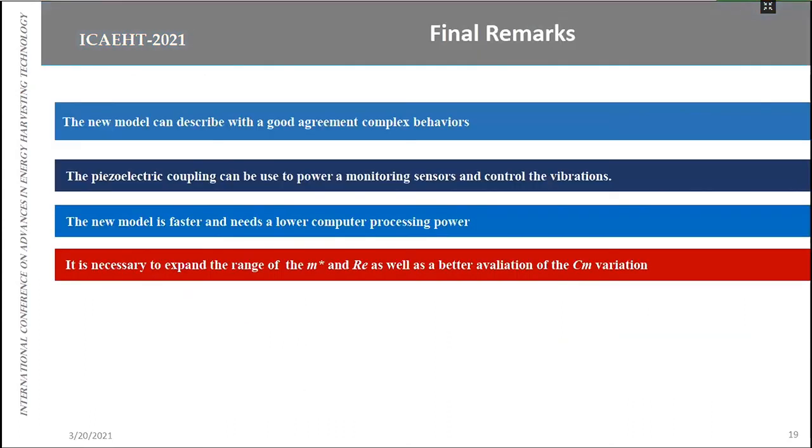As final remarks, we obtained a new model that can describe the complex behaviors with a good agreement. The piezoelectric coupling can be used, for example, to power monitor sensors and then control the vibrations, reducing the amplitude of oscillation. This new model is a faster method and needs lower computer processing power. However, it's necessary to expand the range of the reduced mass and the Reynolds number, as well as a better evaluation of the added mass coefficient variation.